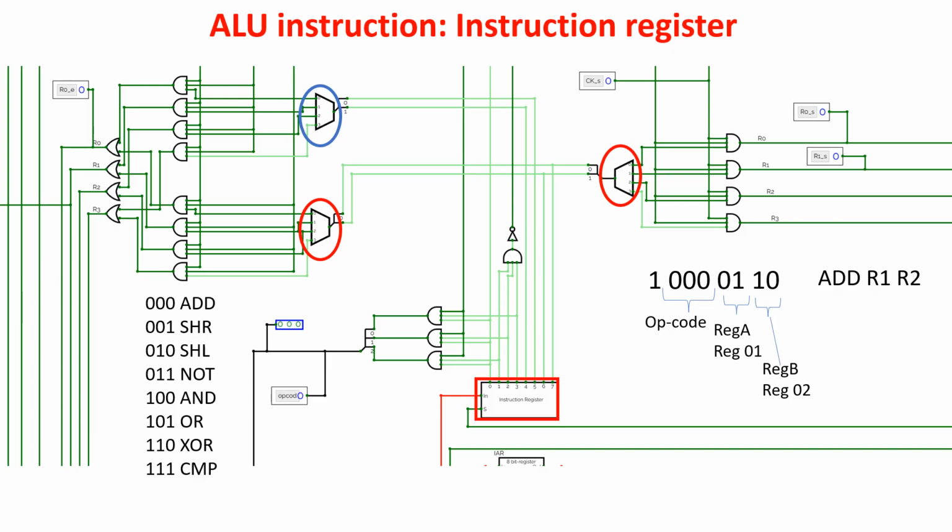In the red rings, the 2 decoders for selecting register B. We give an enable pulse on the left and a set pulse on the right to acquire the result of the operation and store it in register B. The decoder selects the right register, but the right time for the pulses comes from clock enable or clock set, along with the proper step.